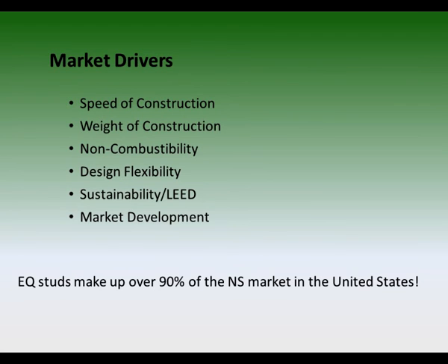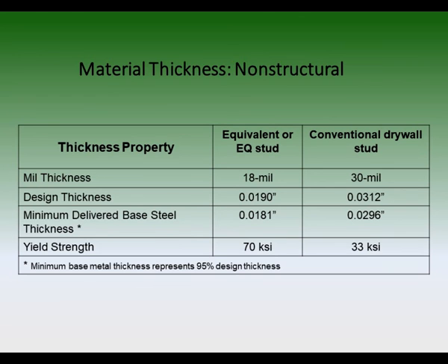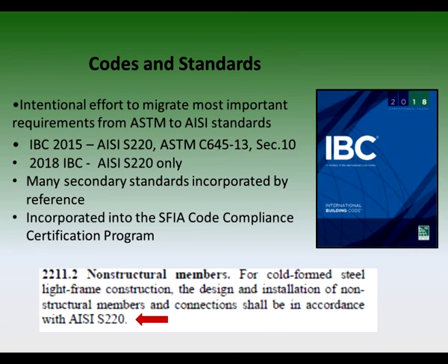There are also some market drivers, as shown here, that make EQ studs appealing. These factors have made quite a transformation, with EQ studs now representing over 90% of the non-structural market. This slide illustrates the difference between the non-structural drywall and an equivalent or EQ stud. The higher yield strength of the EQ stud makes up for the thinner material in this case.